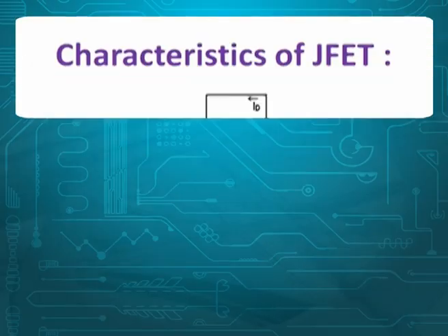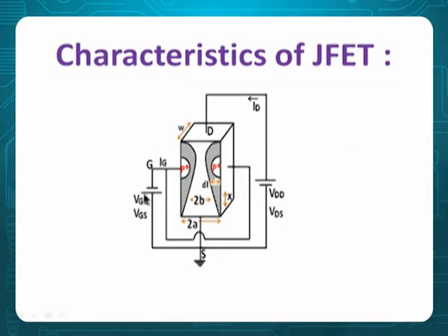Look at here, please look at this carefully. You have given a negative voltage, reverse bias. And I am saying VGG is equal to VGS because there is no resistor and there is no drop. Similarly, VDD is equal to VDS. For different values of VGS, I have to plot ID versus VDS. That is called output characteristics. And for different values of VDS, I need to draw ID versus VGS, the input. That's called transfer characteristics. Good.